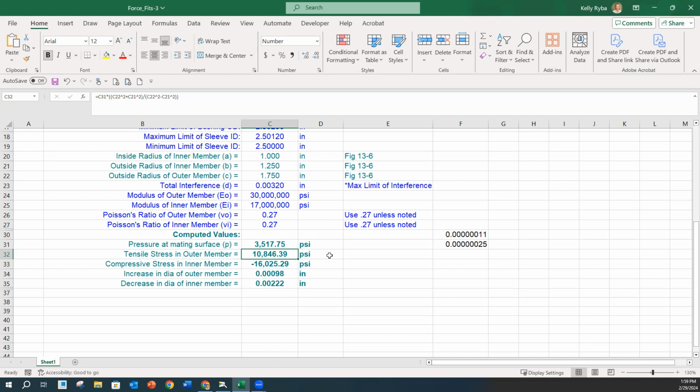Yeah, and I think there is a way to calculate that force too. They don't show it in here, but I think it's also going to just depend on your press. You should be able to back calculate an actual required force. Yeah, you would need to know how long it is so that you can find out what your square inches are that you're distributing over, right? And then you could calculate for the force that would be required and then see if you have a press that could do that.